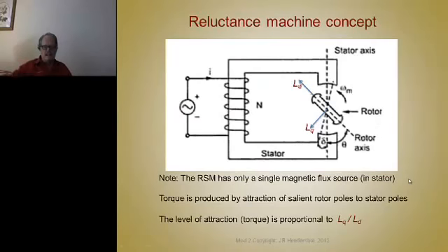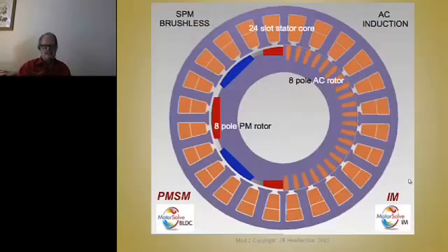So this next slide, we're going to conclude this lecture with, which is quite interesting. How this started is we had a consulting job where we had a client. I think we designed this client. We had a motor, an 8-pole brushless motor. You see the north, south pole, and a 24-slot stator, and of course the coils are wound from pole to pole to create the same number. It's an integral slot winding.